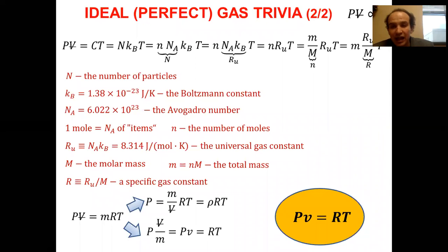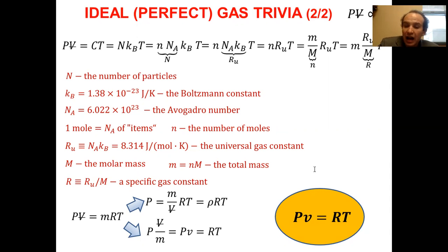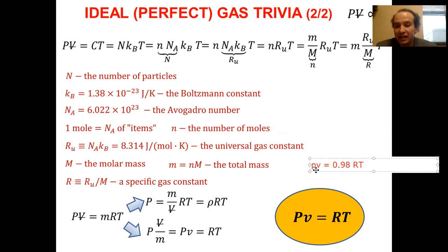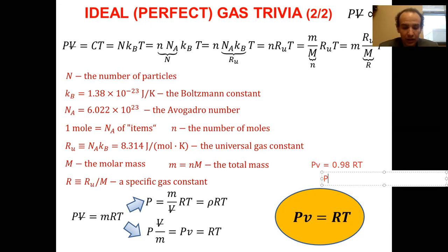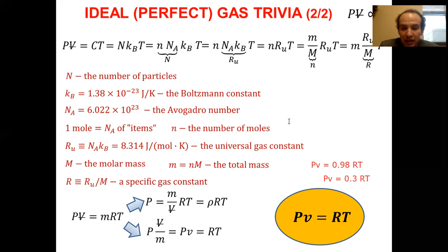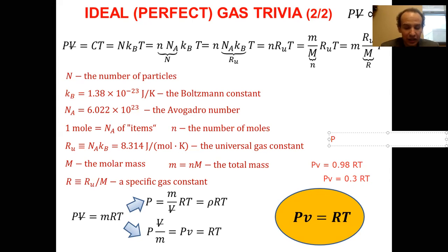But the key point that we discussed last time is that we are engineers rather than mathematicians, right? In reality, of course, there is no ideal gas. So we introduce a way that we can account for it. The equation PV = mRT is still the ideal gas equation. But an equation with an extra factor is not the ideal gas equation. Why? Because of this factor. This factor is Z, the compressibility factor that we introduce. So in fact, we can write the equation like this.